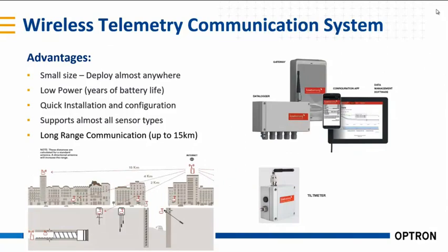At our demo site in Steenbras, which Cobus will come onto in a bit, we've got a piezometer used as a gauge to measure the dam level, and that's about 6 kilometers away, and we definitely do not have line of sight, and the system operates seamlessly. It's very low power. It comes with internal batteries that can last literally years, depending on the measurement frequency. But if the frequency is 2 hours plus, they can last in excess of 5 years. Very quick to install, and you can connect practically any common sensor on the market to these data loggers.